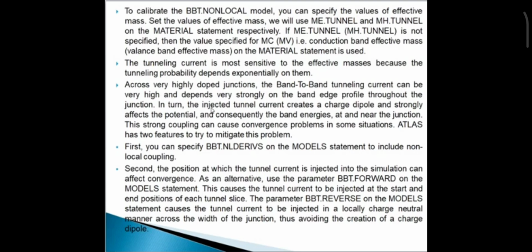First, you have to specify BBT.NONLOCAL.COUPLING on the model statement to include non-local coupling. Second, the position at which the tunnel current is injected into the simulation can affect convergence. As an alternative, use the parameter BBT.FORWARD on the model statement. This causes the tunnel current to be injected at the start and end position of each tunnel slice.